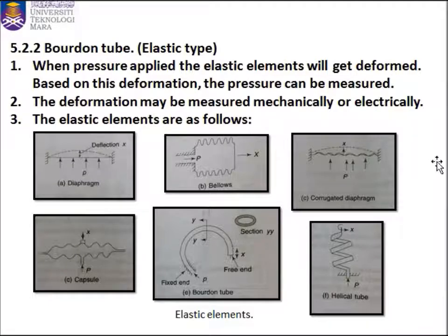Next we move to Bourdon tube, elastic type. For elastic type, the keyword is deformation. When pressure is applied, the elastic elements will get deformed.